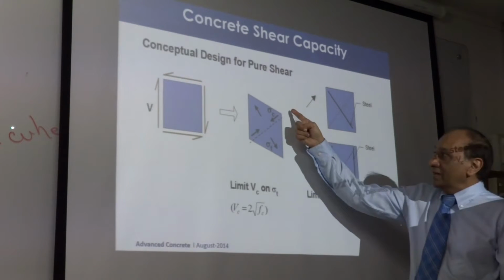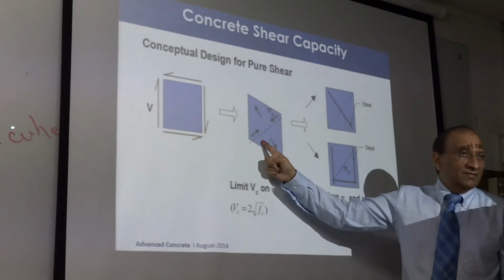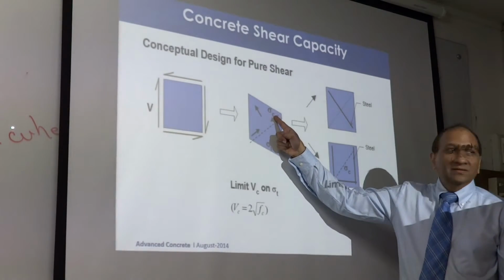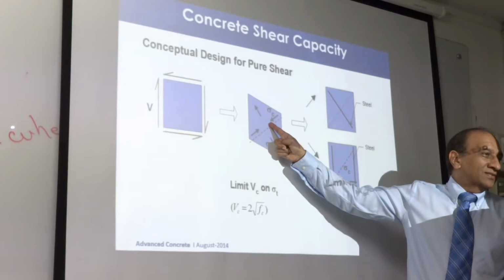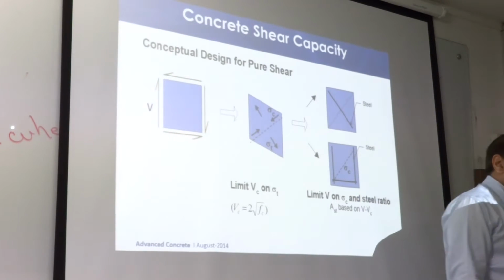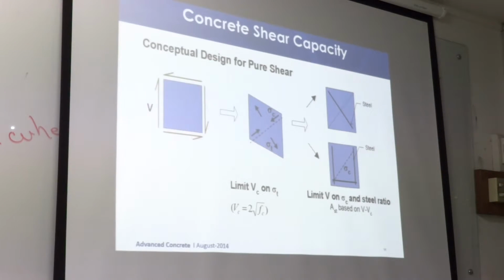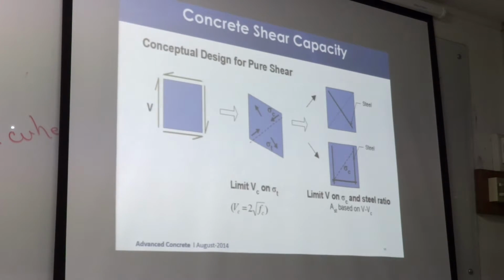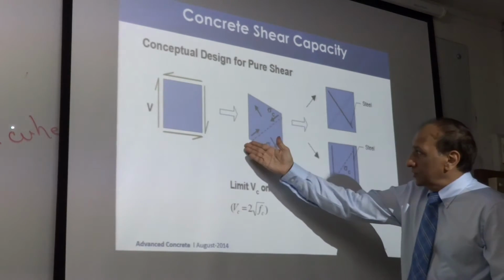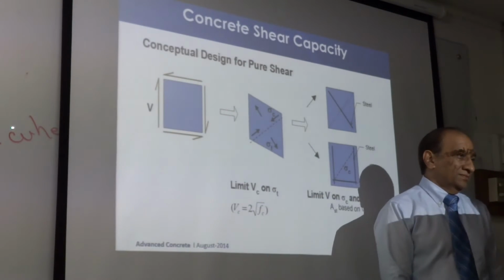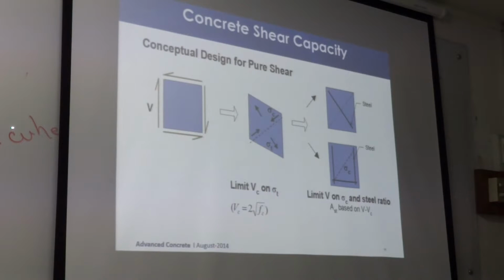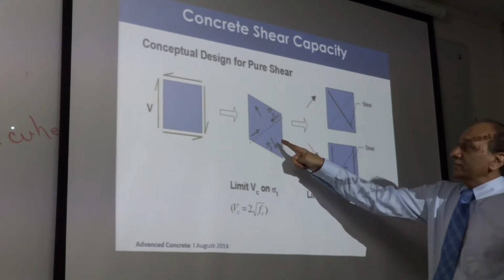And this becomes our principal plane where there is no shear, only tension and compression, or axial stress, is left. Correct? From the Mohr circle, there will be a plane where shear will disappear, and we will get that plane on which only tension and compression exist. No more shear. Shear has been converted into tension and compression, and that's what we were talking about. That one of them must be tension, one of them must be compression.